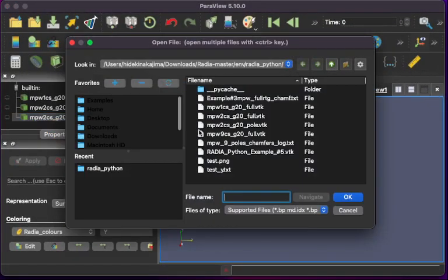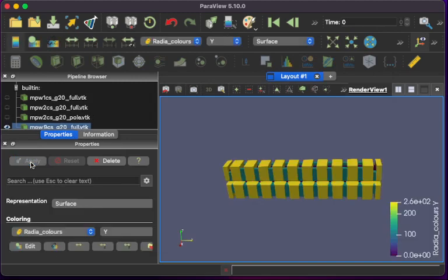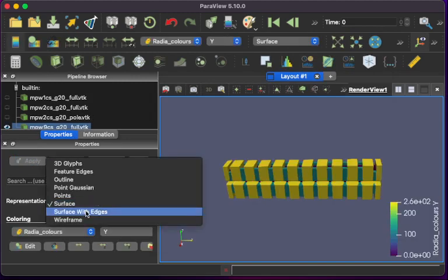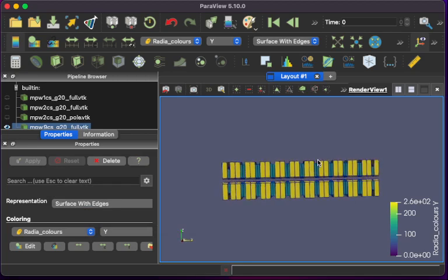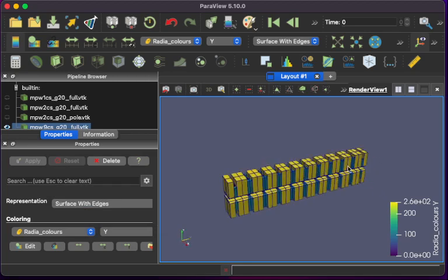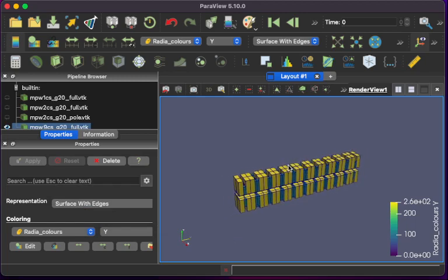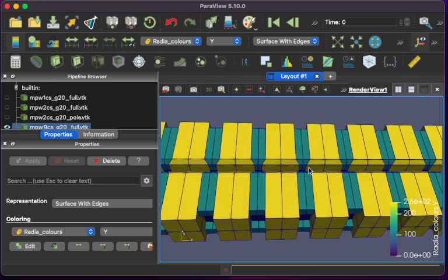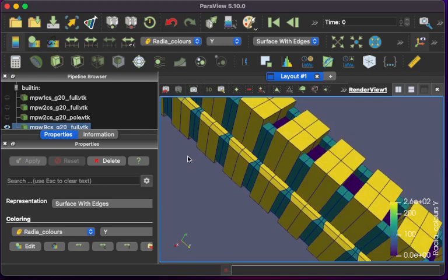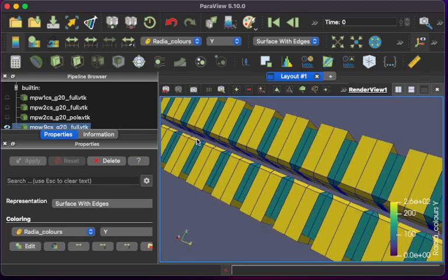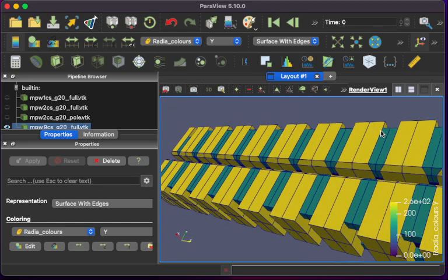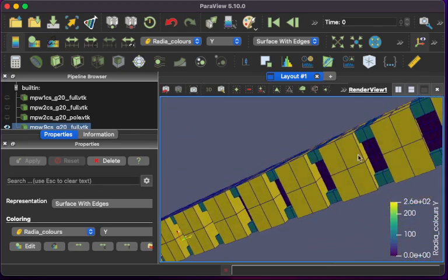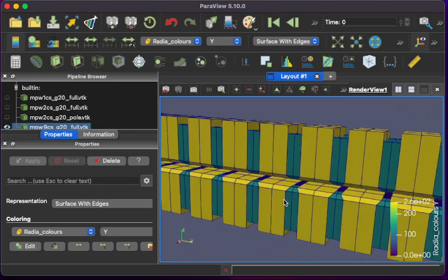So finally, I would like to show this VTK for the 9-pole configuration. As you can see, 9 poles in between the ending poles. You can also magnify for detail to check whether your model is correct or if there is any overlap between the magnet or side or pole, and check whether the model is correct or not. You can see that.